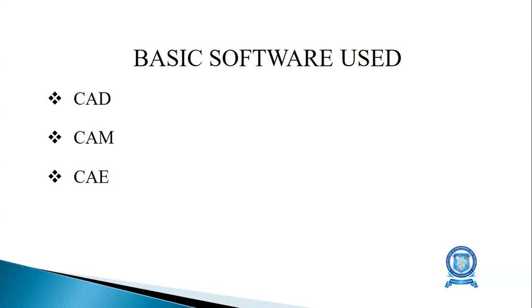CAM, computer aided manufacturing, is software or a program used to extract the technical information from the CAD model and generate the machine program necessary to run the CNC machine and manipulate the tooling to produce the custom designed part. The CAM software enables the CNC machine to run without operator assistance and can help automate finishing and product evaluation.